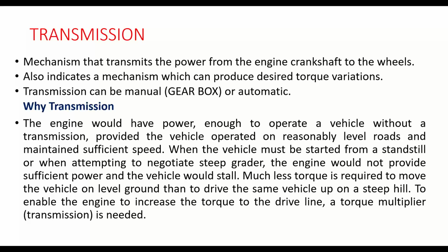Once it starts moving, the amount of inertia will be less. So in the second gear, again the torque ratios will be varied and smooth movement will be there. This transmission system can be either manual or automatic. Whatever you can see in a scooter like Honda Activa is the automatic system. Based on the accelerator itself, automatically the gear will be shifted. What you see in a bike, motorcycle, is a manual gearbox. You need to judge by yourself.